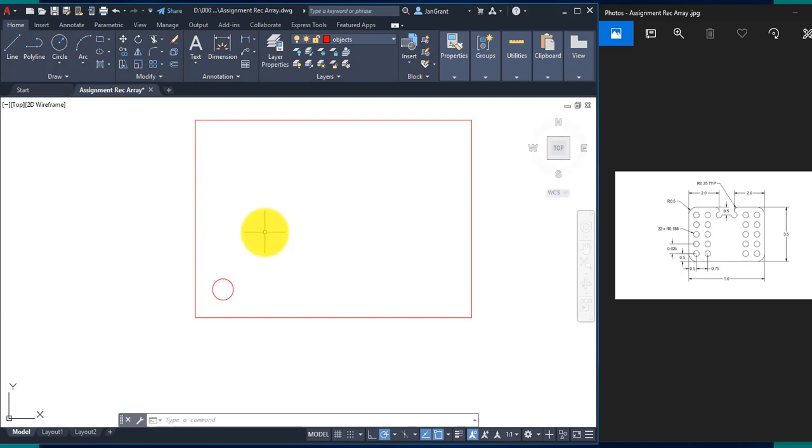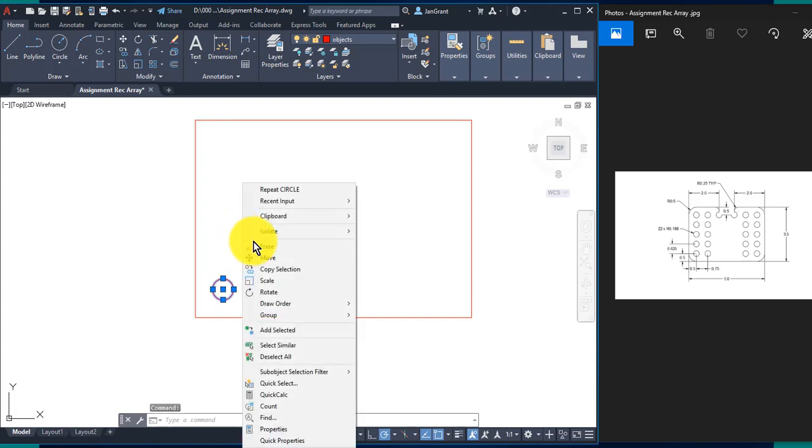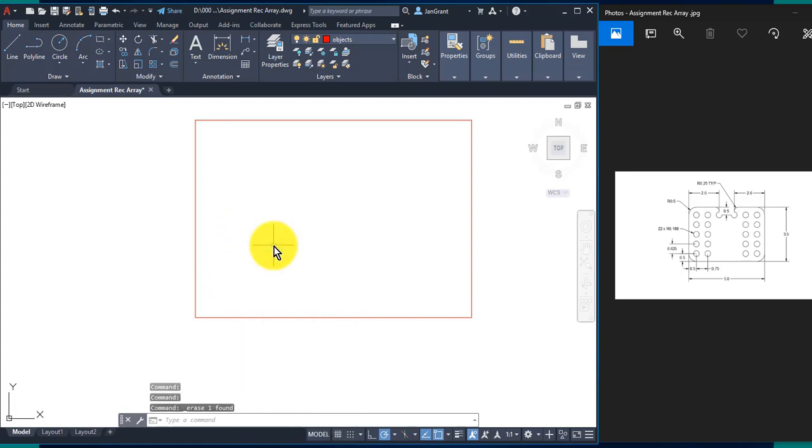Instead of just tracking from this object snap over, we went over and up using TT for temporary tracking to set this little alignment point. If that is not working for you, I'm going to do this again here the way we've been working with offset, right? And that's good practice as well. I just erased that circle. I'm going to start the offset command.